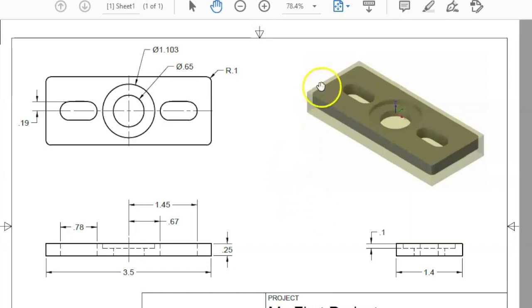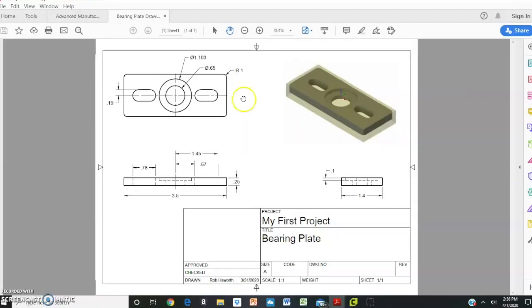So that profile will be removing a little bit of material just off of the outside because we only have a piece of raw material that's only slightly bigger than the outline of the part that we're actually making. So the part that we're actually making is 3.5 inches long and 1.4 inches wide. And it has corners that have a 0.1 inch radius. Let's see how that works out in PathPilot.